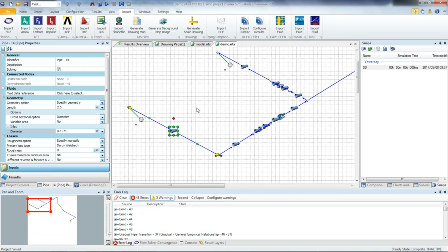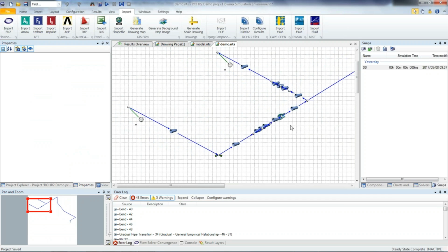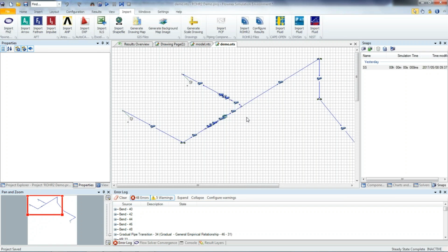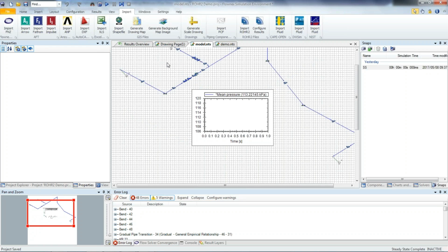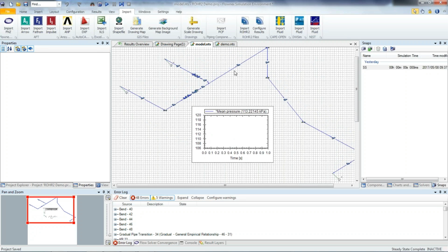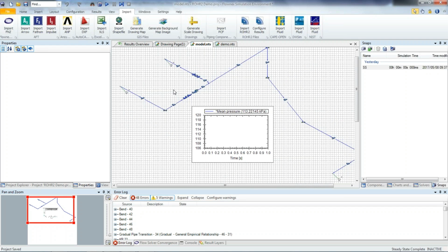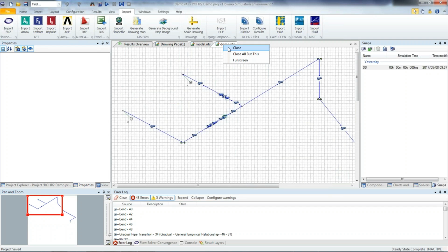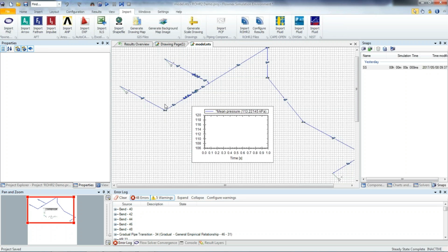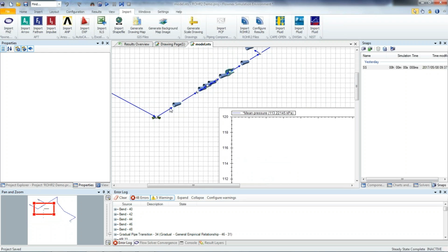Okay, so all that's necessary to actually solve the simulation is to specify a couple boundary conditions, specify a fluid that we'd like to use, and then to configure a transient simulation for the valve closure event. So just to save a little bit of time, I've pre-configured that in this little network over here. It's an identical copy of what we had, just with some of the boundary conditions specified. I've created a little graph over here to display the pressure upstream of the valve.